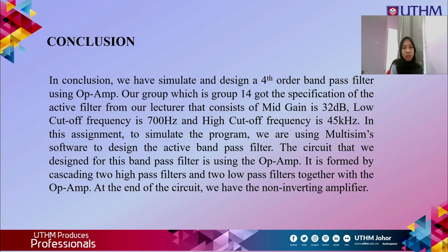In this assignment, to simulate the program, we are using Multisim software to design the active bandpass filter. The circuit that we designed for this bandpass filter is using the op-amp. It is formed by cascading two high-pass filters and two low-pass filters together with the op-amp. At the end of the circuit, we'll have the non-inverting amplifier.